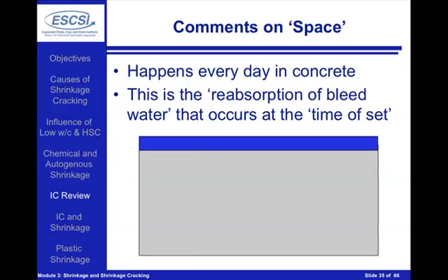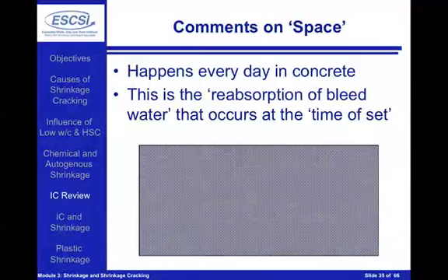In other words, this is really correlated to the time that an underpressure starts developing in the fluid that pulls this additional water away from the surface to make sure that we're minimizing the vapor-filled spaces that are forming inside of our concrete. So once our concrete sets, water gets reabsorbed back into that concrete, reducing this underpressure that's forming inside of the system. So this concept happens every single day.